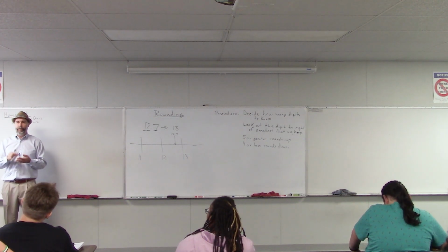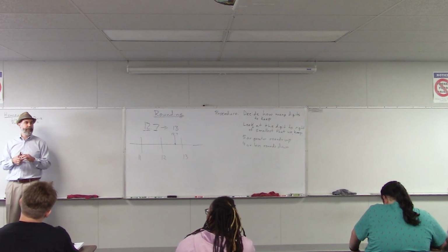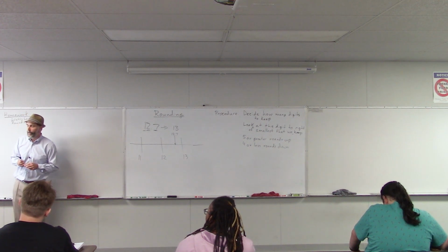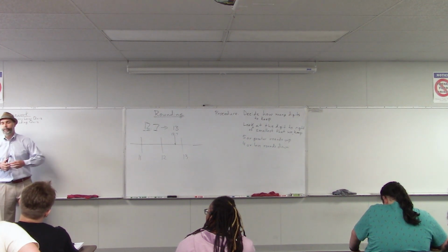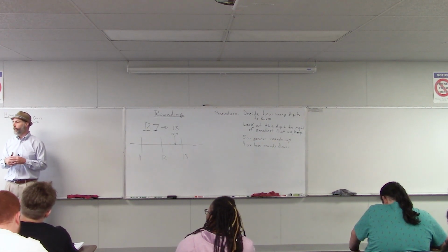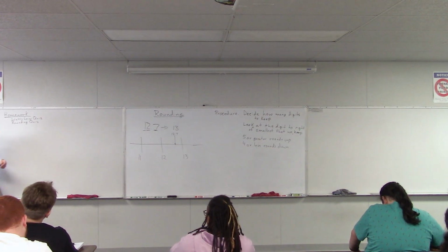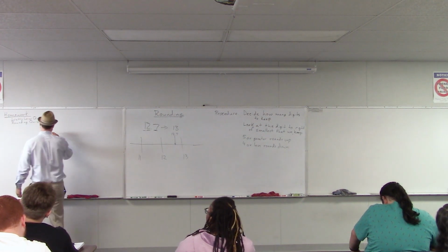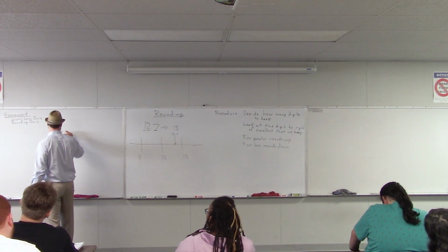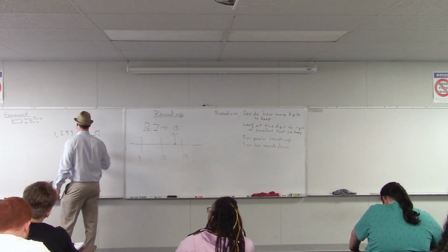Whereas with the resistors that we use in class, what's the common tolerance on those resistors? Yeah, about 5%. And those resistors often vary their resistance based on temperature. So with something like that, you might get a measurement of 1,253.687 ohms or something, right?